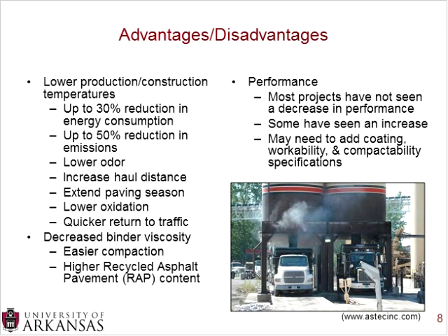You can also have a longer haul distance, because if you start out with a cooler mix, it won't drop as quickly as you haul it. And you can extend your paving season. Because of those lower temperatures, it's a little more kinder as the temperature starts dropping. And also, because it doesn't need to cool down as much after placement, you can have a quicker return to traffic. So these are all advantages that are pretty much direct byproducts of the lower production and construction temperatures.